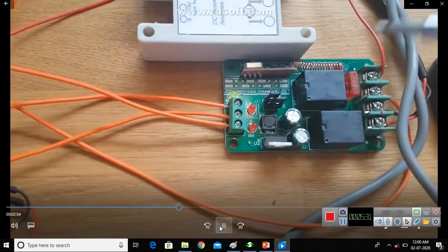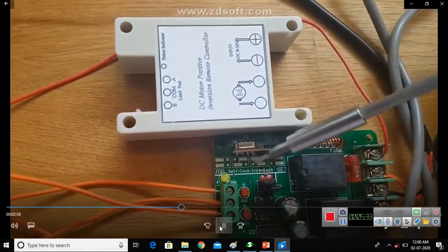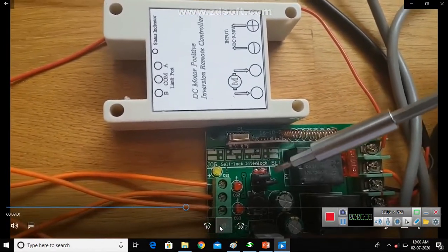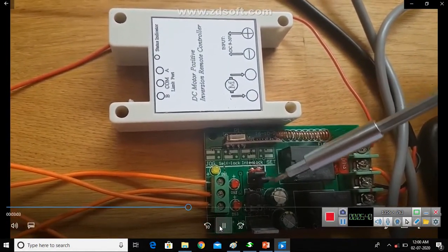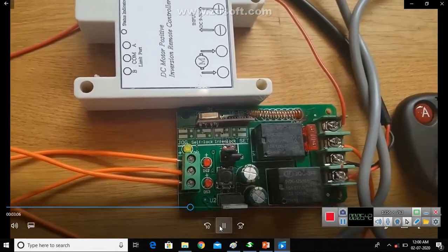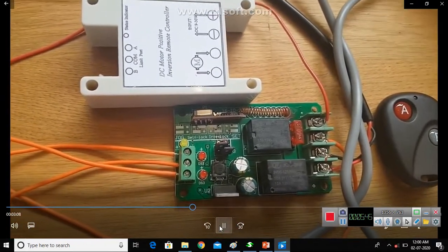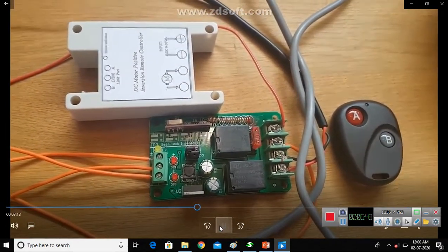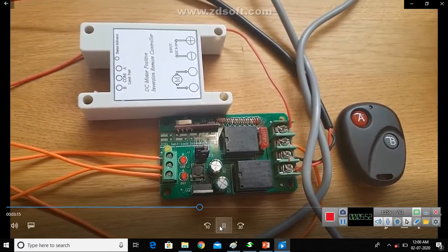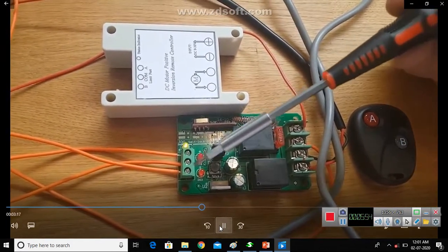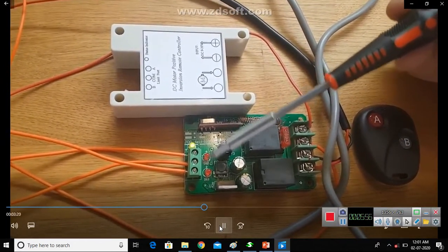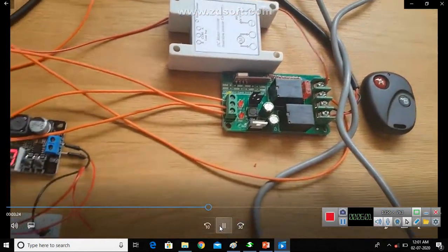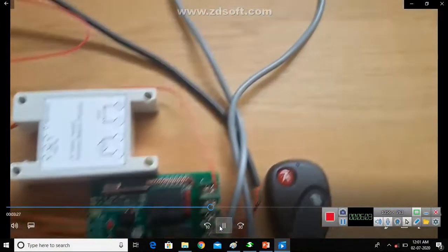And then if you can see on the actual printed circuit board here, you can have interlock. If you put these switches here, look, these dip headers here, you can set this board to be interlocked, which means it will run continuously rather than being in a kind of jog mode, which means you keep your button on it to run the motors. And this means it's going to wait for an interlock. It's going to wait for these switches to tell the linear actuator circuit when to stop. So I'll just go back to the proximity sensors.